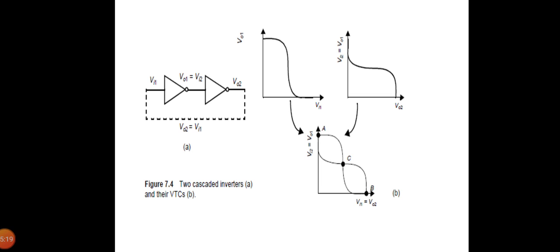Since the precondition for stability is that the loop gain G is smaller than unity, we can achieve this by making A or B temporarily unstable by increasing G to a value larger than 1. And this is generally done by applying a trigger pulse at Vi1 or Vi2.